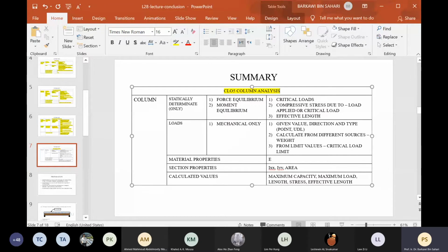Yeah, because I think question number 4, if I'm not mistaken, because the earlier question is actually not much of an exercise. It's basically filling the numbers into an equation. Just P crit equal to pi squared EI over K squared L squared. And for different boundary conditions, just put in all the values there in your calculator and you get P critical. So to me, not much in there, except know what value to put into that equation. But I think the fourth question requires some, what you call thinking, and this course is about thinking.